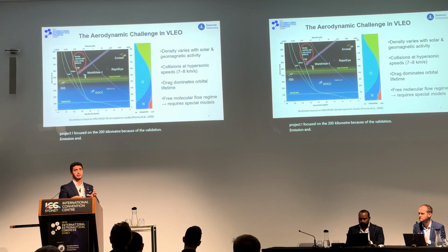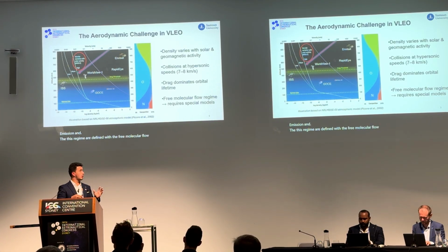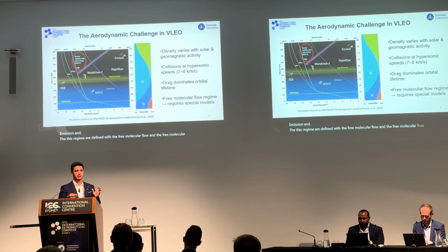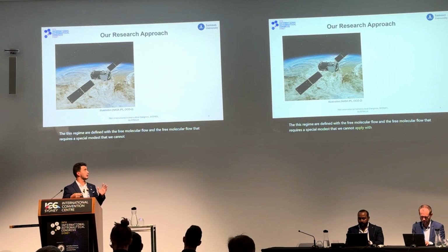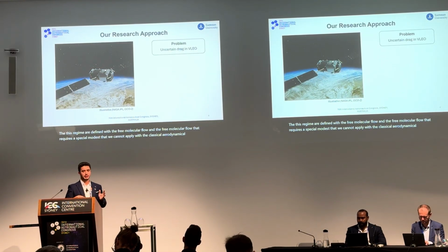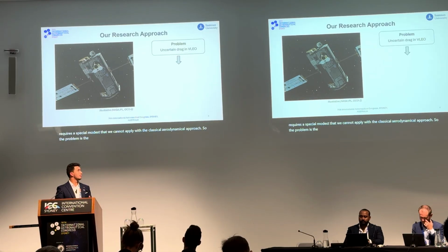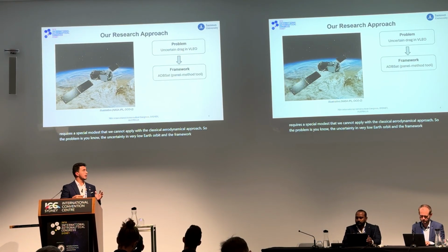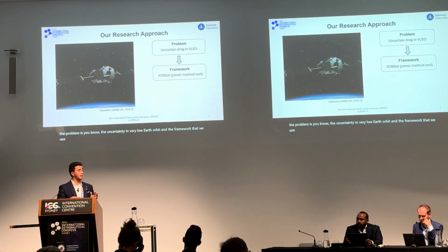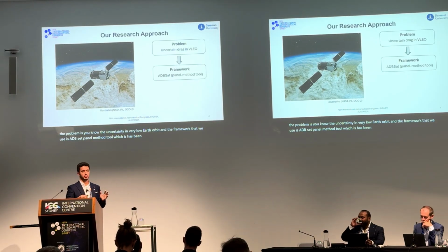this regime is defined by free molecular flow, and free molecular flow requires special models that we cannot apply with the classical aerodynamic approach. So the problem is the uncertain drag in very low Earth orbit, and the framework that we use is ADBSat, a panel method tool developed at the University of Manchester.